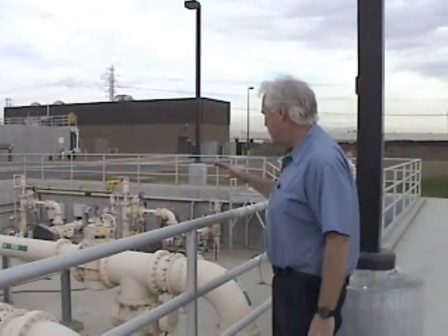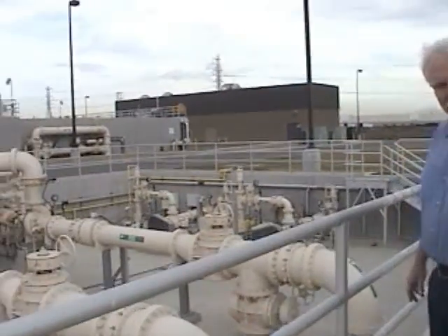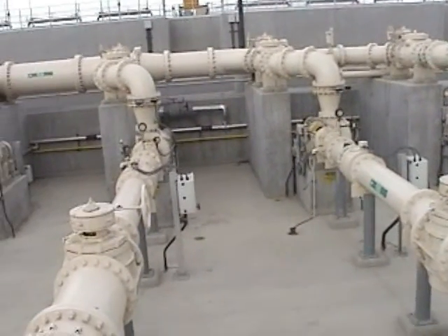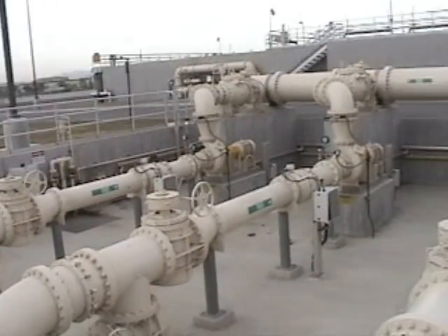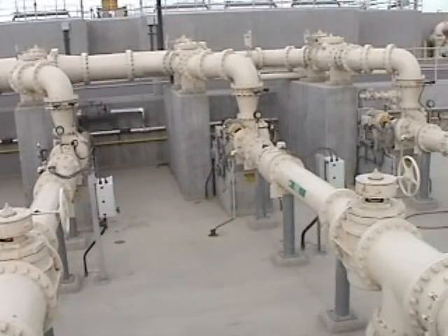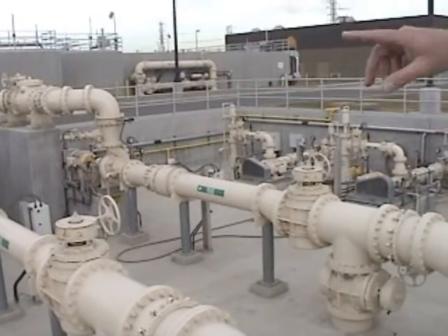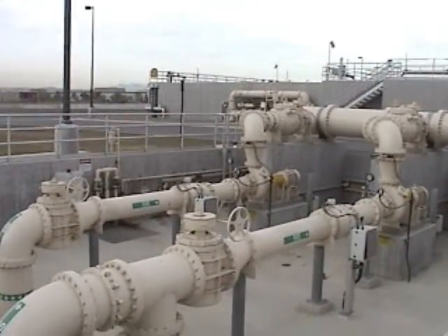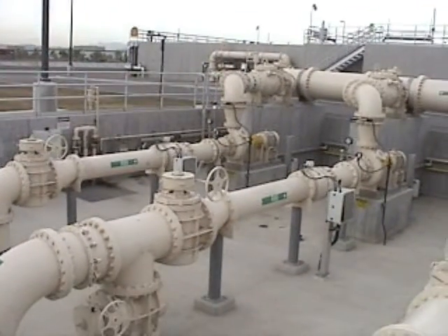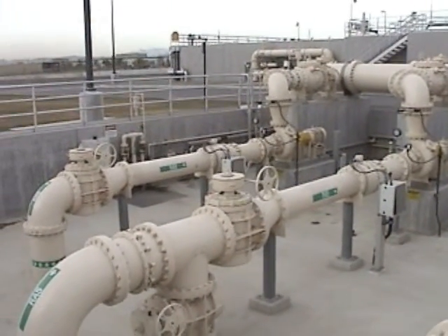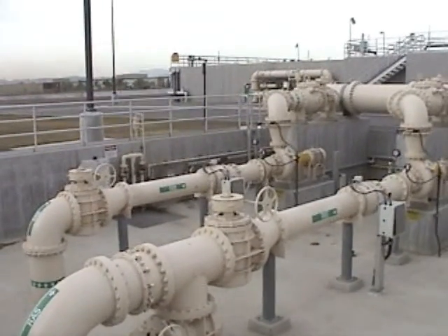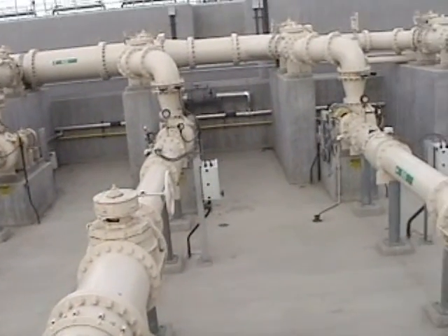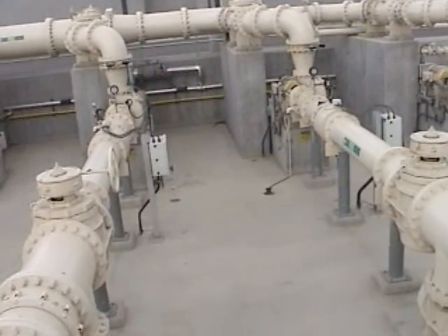This is the RAS pump station right here, and each secondary clarifier has a dedicated RAS pump: 4 clarifiers, and here are the 4 pumps that handle the job. In the event of a problem, if we have to pull maintenance on one of the RAS pumps, we can use RAS pump number 10, which is the one on the end. You can see it's a little bit different because of the valving and things like that below. The reason is that RAS pump number 10 can be used in place of any of these other RAS pumps by changing the valving down at the base of these pumps.